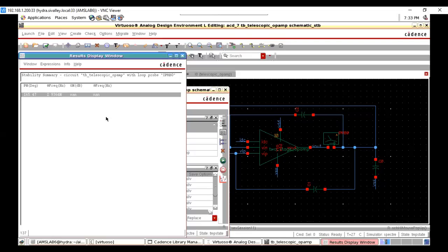That is also an important topology. It's just an improved version of the telescopic, even in the derivation. Just take an overdrive voltage of 200 millivolts, start deriving the W values, and see the simulation results in the lab. If you face anything, let me know.